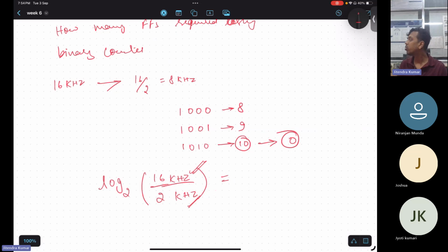So basically, we use as many stages of flip-flops as reduce your frequency. Why do they reduce the frequency at the output? Because most of these ripple counters are asynchronous, so the second flip-flop will be waiting for the pulses coming from the output of the first flip-flop, and the third flip-flop will be waiting for the output of the second flip-flop.